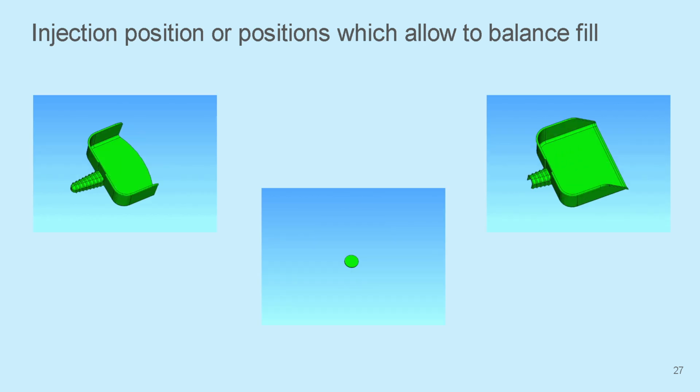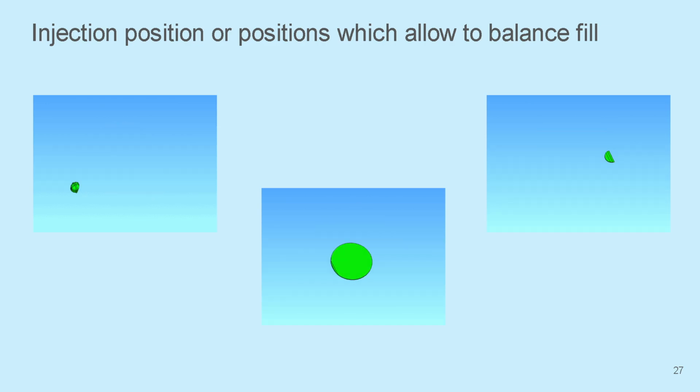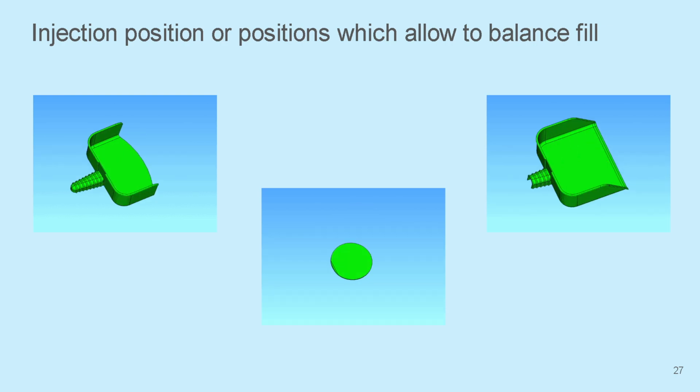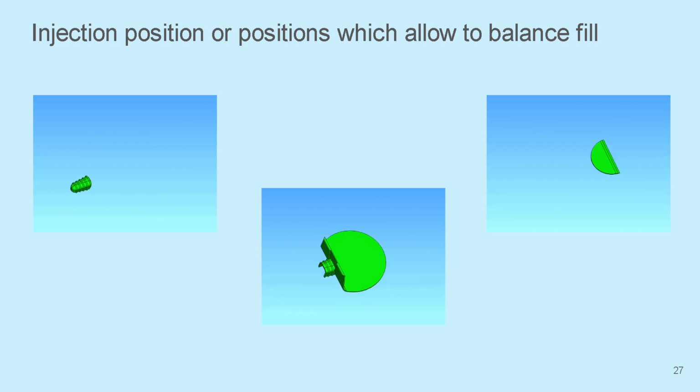And now, one of the most interesting topics in injection molding. Filling the nest. We see three possibilities for filling the dustpan. We see two injections from the side, filling along the part, and one position where injection is from the middle of the part. Injection from the middle is faster. Melt has half of the part distance. Fill is more balanced with this solution. Pack phase will also be more effective.